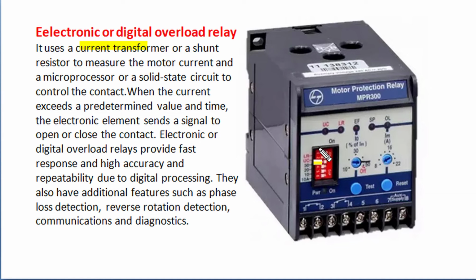Such digital or numeric overload relays provide fast response, high accuracy and very good repeatability due to their digital processing. They have additional inbuilt features such as single phasing protection and reverse phase sequence protection, and they also provide remote control, telecommunication and telediagnostic services.